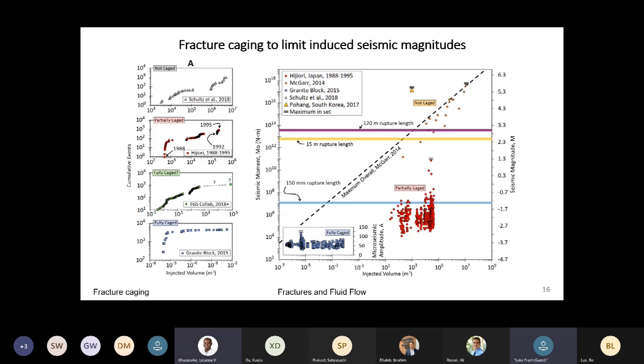Okay. Thanks for that. Yeah, so I prefer to think about hydraulic fracture propagation as a volume balance problem versus any sort of stress problem. They're definitely related, and that's why it's in all the theory. But when it really comes down to it, if you're leaking off faster than you're injecting, your fracture is not going to be growing, because if it tries to, the pressure has to drop at those extremes, and it just can't, basically.